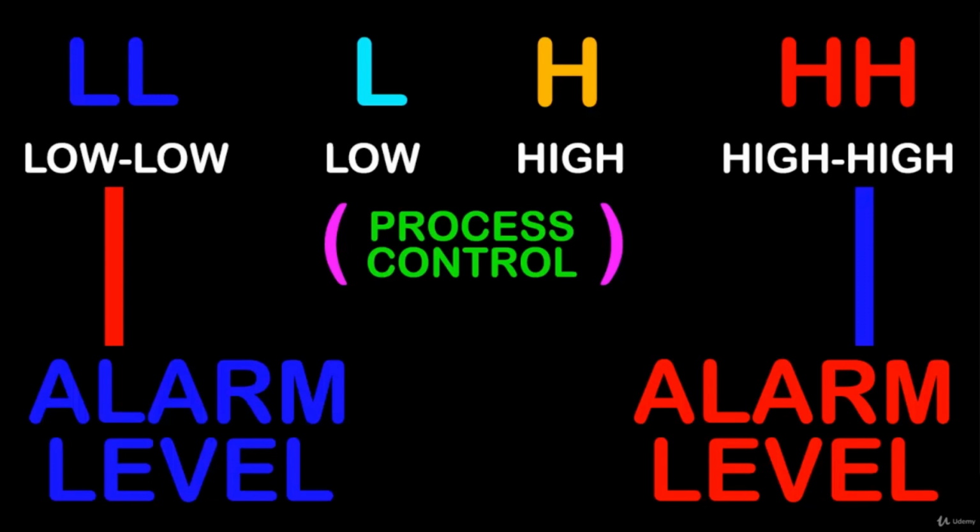So in our program, we have a low and a high limit programmed into our control logic. When the temperature gets below 70 degrees, we turn our heater on and we latch it on so that it stays until our temperature reaches a high set point, and we'll set that high at 80 degrees. So as long as our temperature doesn't fall back down to low, our heater won't come back on, but it'll bounce, assuming that the ambient temperature is of course below our low set point.